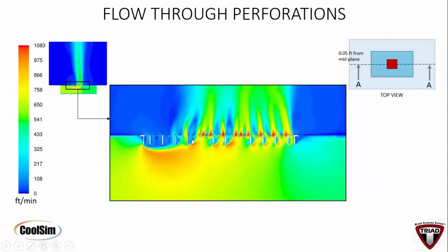This one is going to create a situation where you've got recirculation on that leading edge because of this piece of geometry. So this tile is not a good tile for cooling a data center. It's got two problems with it as far as I can see, Gary. One, the jet is very small and concentrated and very, very high velocity. And number two, the cold air is going up to the ceiling.